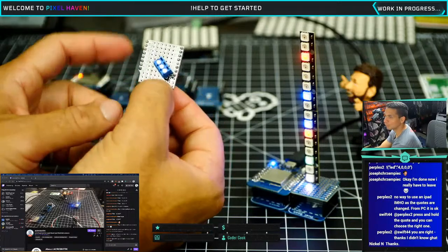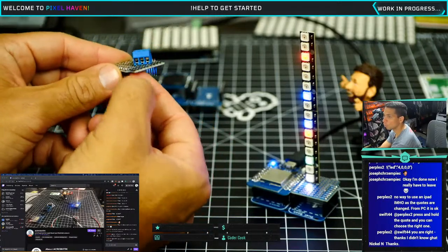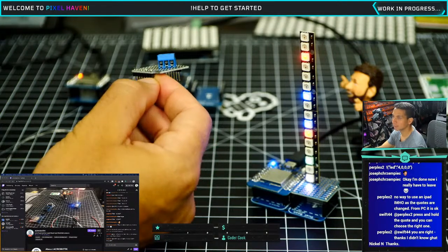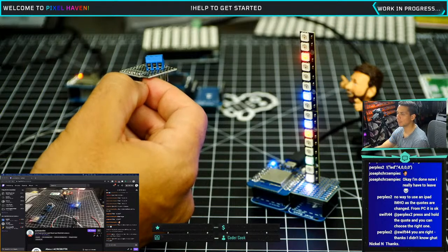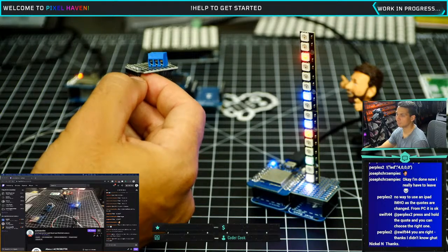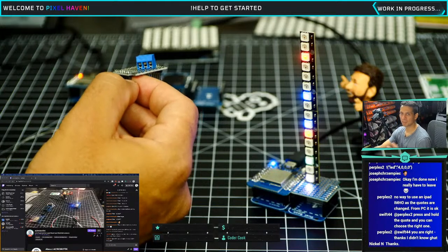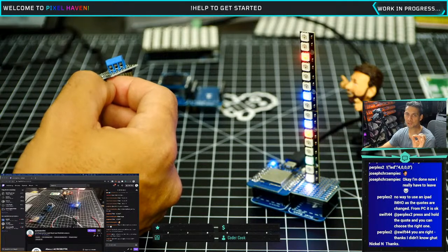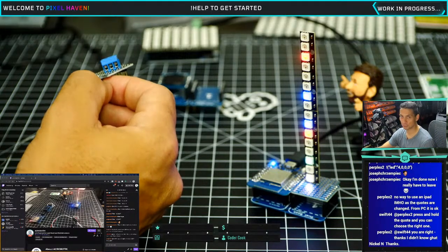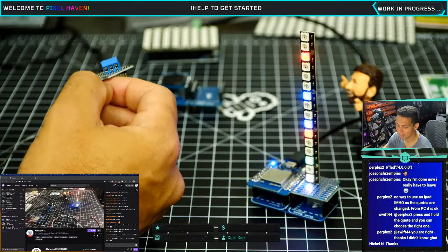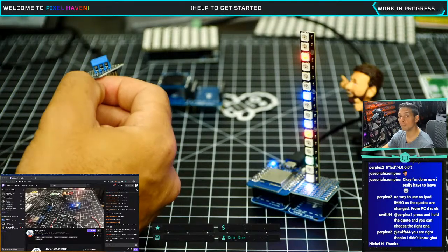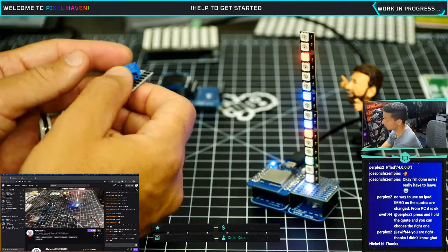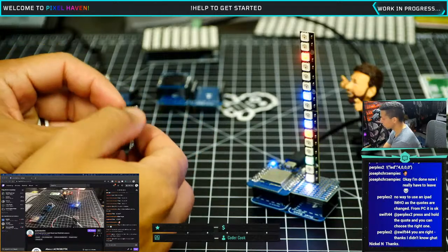And you might wonder, why don't I get 0.1 inch pitch terminal blocks? And yeah, that's a little bit too close together for comfort to have two cables, even though it's not high current. Particularly, we use a lot of stranded wire, and there's always one strand that doesn't go in, so just that extra bit of separation, which you might not think is much, what is it, not even a full millimeter, but it does make a difference in my opinion. And yeah, you're welcome to try it out.